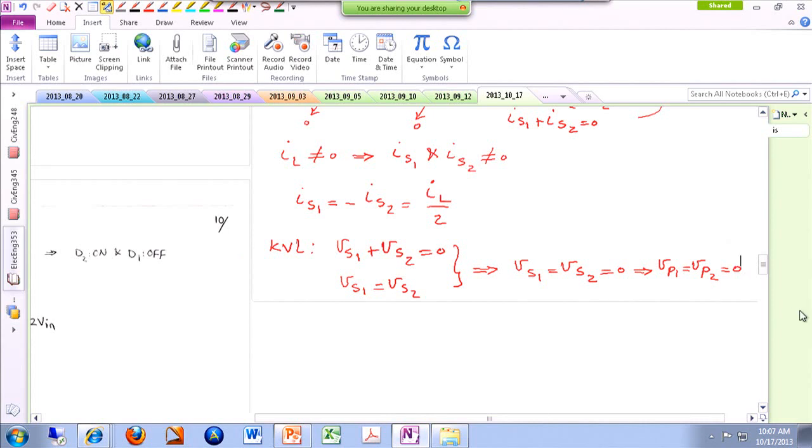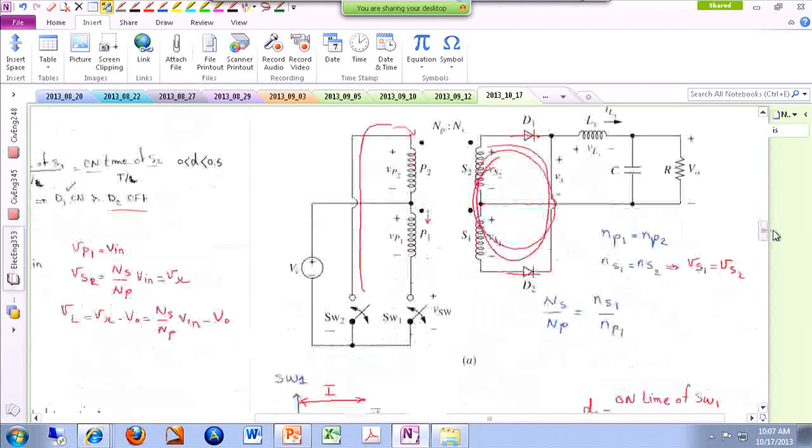So technically, in this particular mode, mode number 2, which is a strange one, from here to here I have 0 volts, and from here to here we have 0 volts. So if we apply, for instance, KVL over here, you can see how much voltage is applied across your switch in this mode that is off.